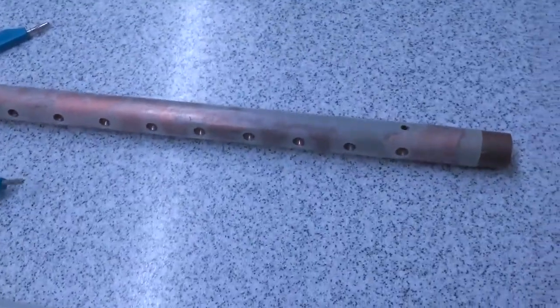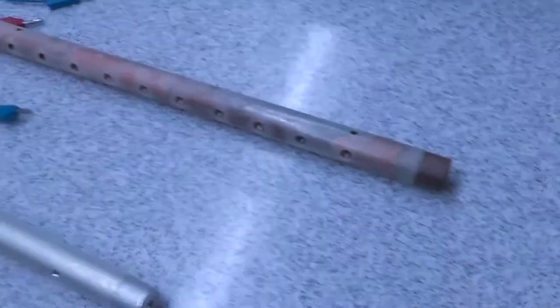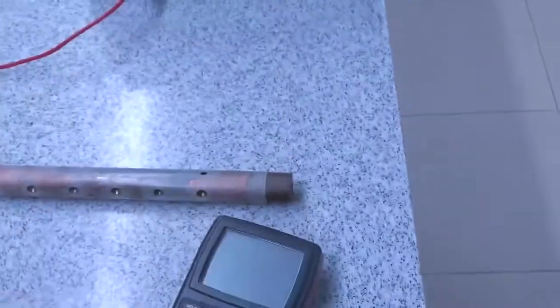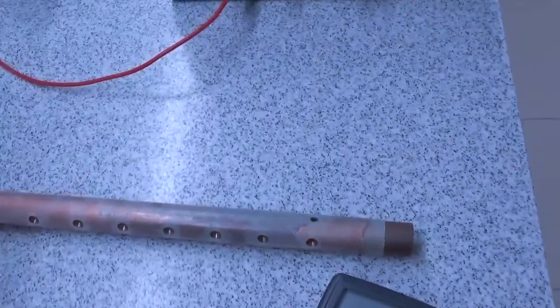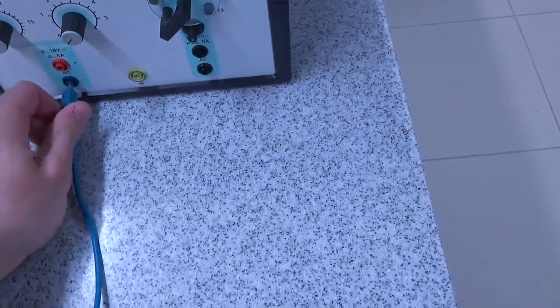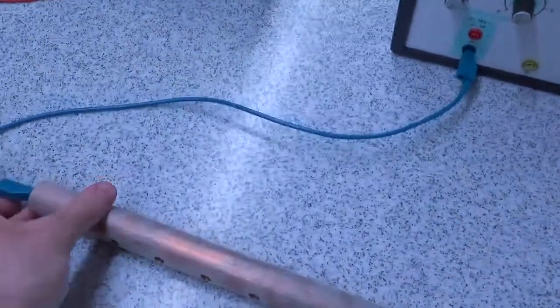So for the first part, they ask you to connect in series the copper rod with that power supply and with an ammeter. So the ammeter, the copper rod, and the power supply are going to be connected in series. So for that matter, we are going to bring one connection from the ground or from the negative terminal over here, and we are going to connect it to one end of that rod.